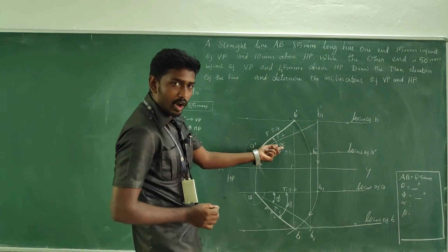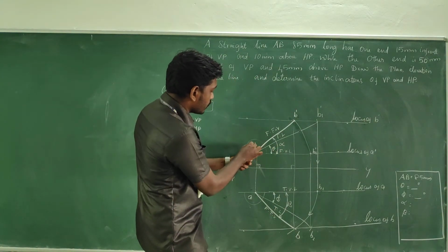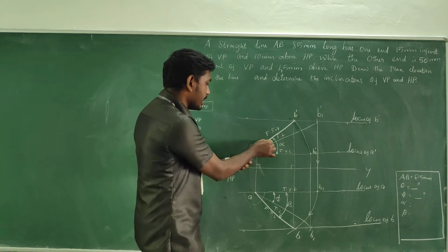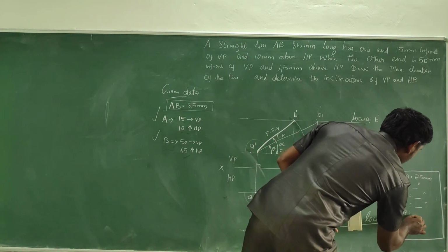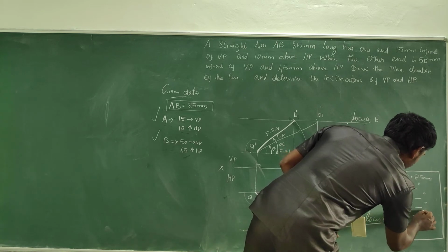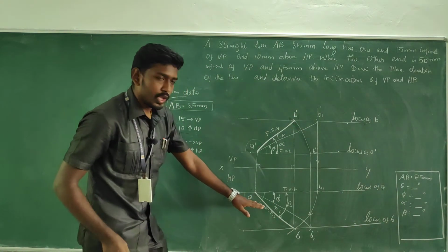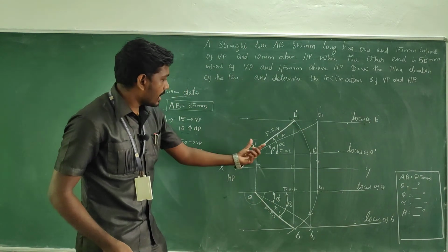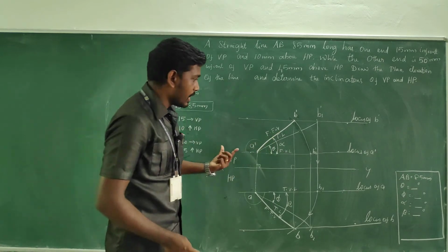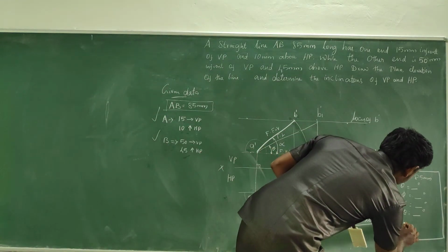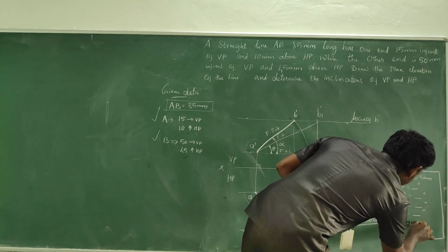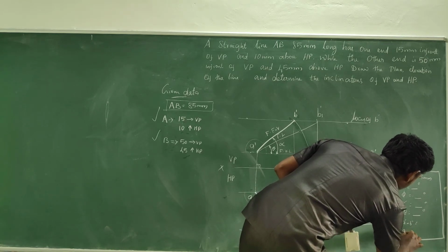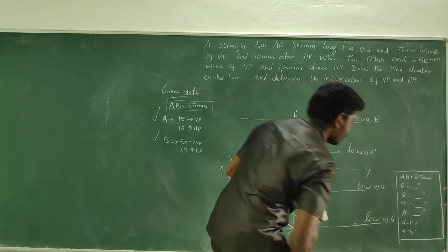In the same manner the alpha angle also, by keeping the position of your protractor like this, you can read the angle in degrees, and as well beta from the top view you can read. And also the final front view length should be measured, that means A dash to B dash, and A to B, you should measure it.